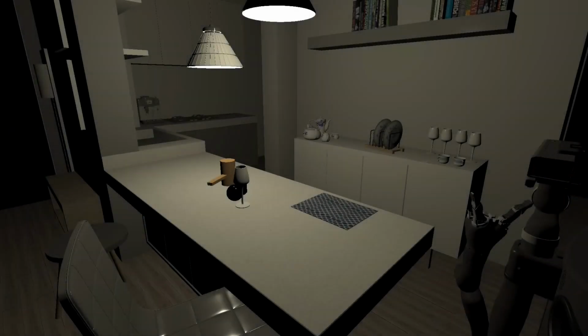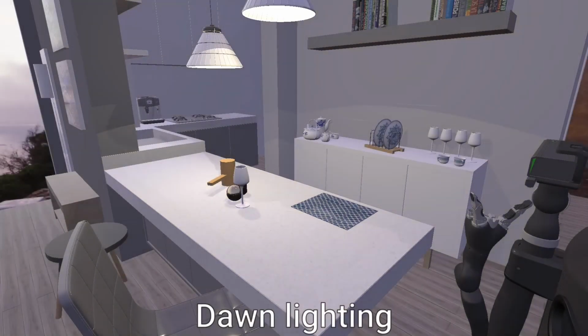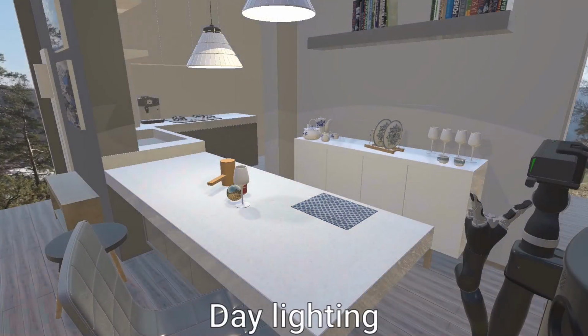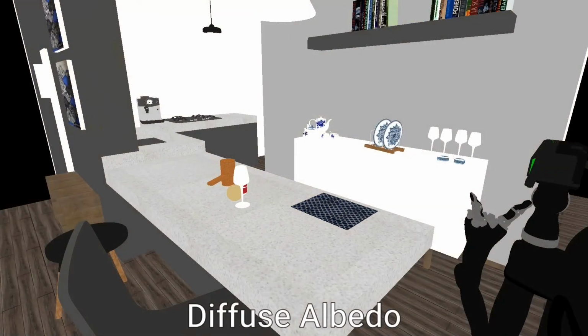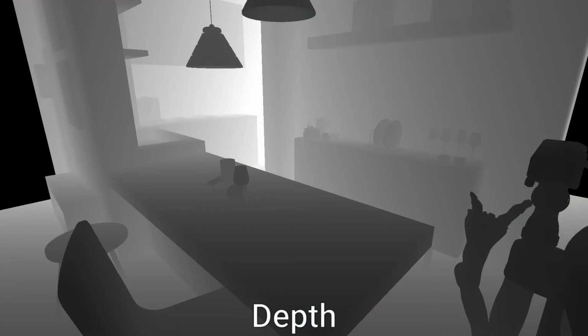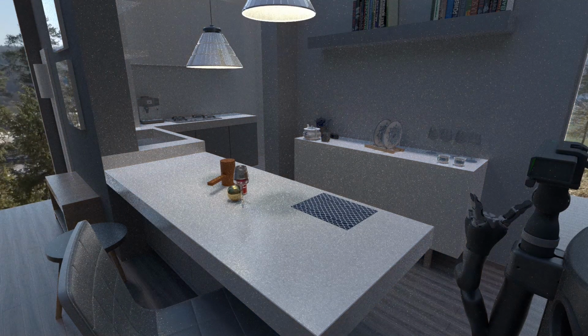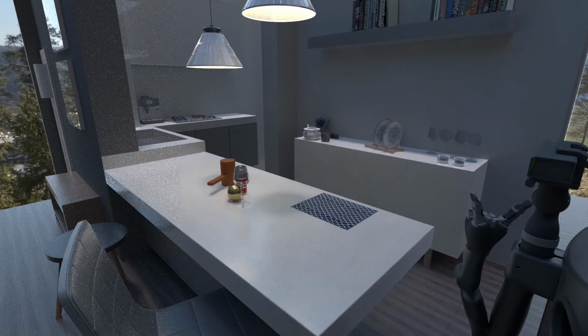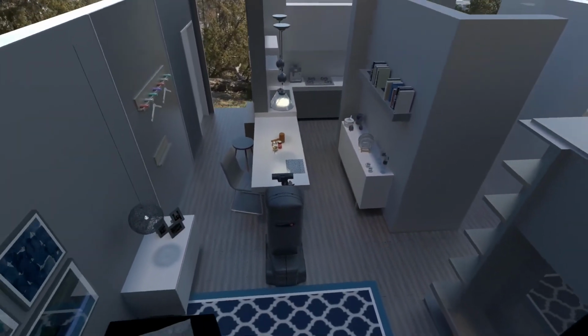Let's start from the renderer. On top of the real-time renderer provided in SAPIEN 1, SAPIEN 2 has allowed an unlimited number of shadow casting lights and ambient lighting from environmental maps. The renderer is now implemented in Vulkan with customizable shader pipelines and render targets, such as albedo, normal, and depth. If you want to render photorealistic images, SAPIEN also comes with a ray tracer, with an optional denoiser when using an NVIDIA GPU. The ray tracer also enables realistic depth sensor simulation through active light.